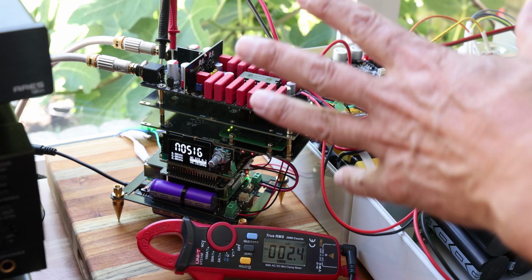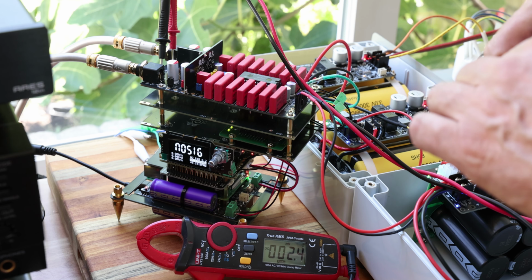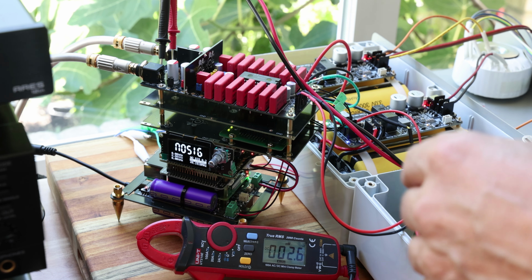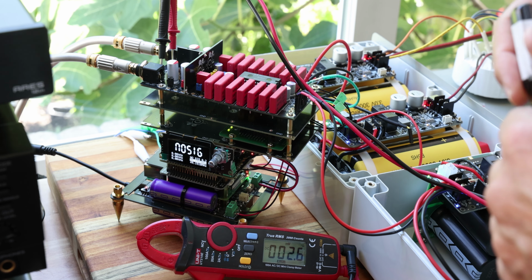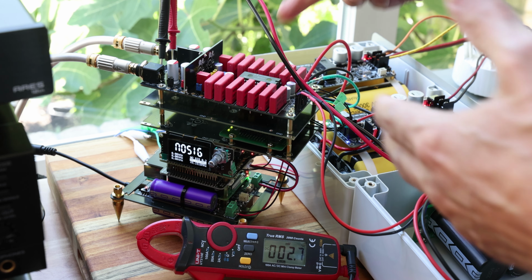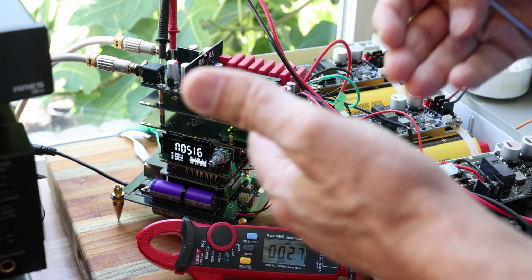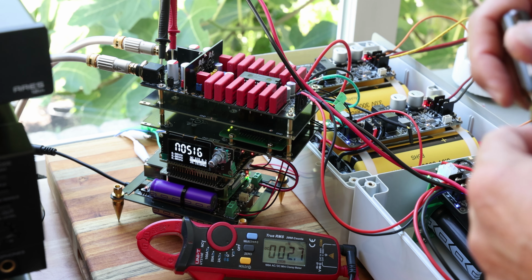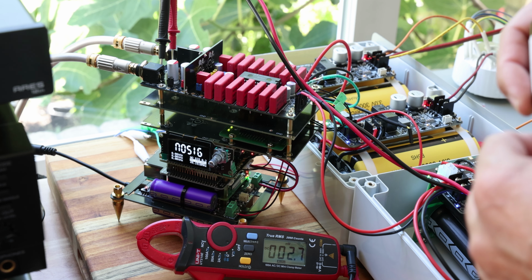Please note that the DC offset comes from the TDA chip. It's not part of the IV stage, the amplifier stage. The TDA will produce a bit of voltage, the amplifier will amplify it, and that's how you get up to 2.3 volts at the end.